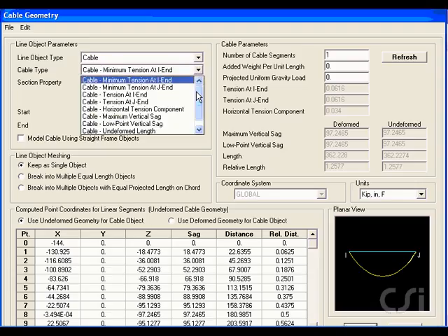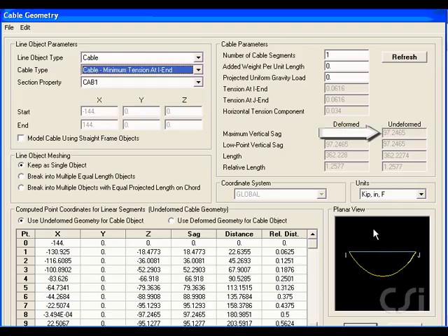The first choice is a shape that gives minimum tension. For a 1-inch diameter cable spanning 288 inches, this tension is 0.06 kips at the ends. The sag for this cable is 97.2 inches in the deformed state. This includes strain deformation, and virtually an identical sag in the undeformed state with no load. The program also tells us the relative lengths for the two states in comparison to the chord length of 288 inches. The program uses this information to generate point coordinates for 17 points along the cable to define the shape.